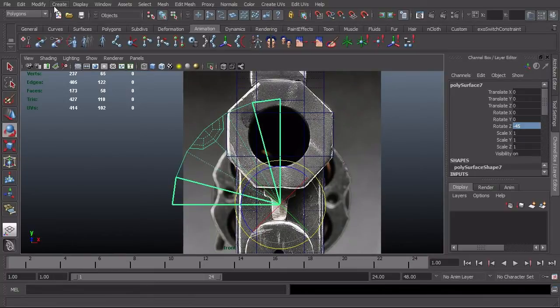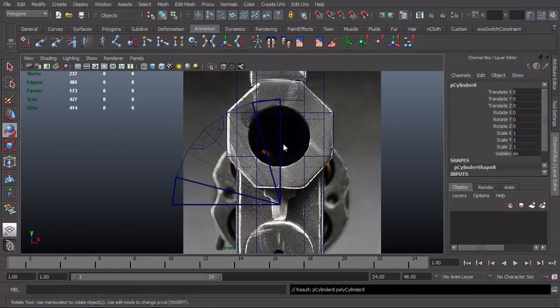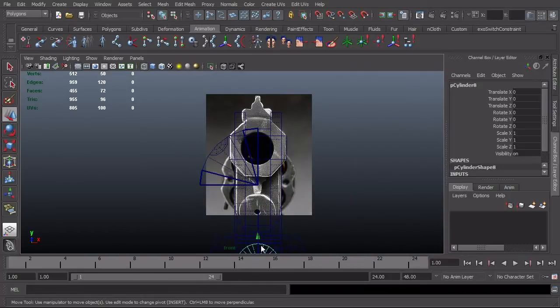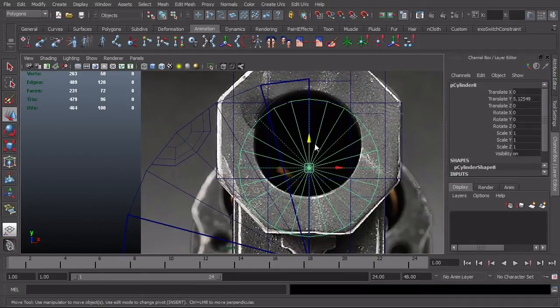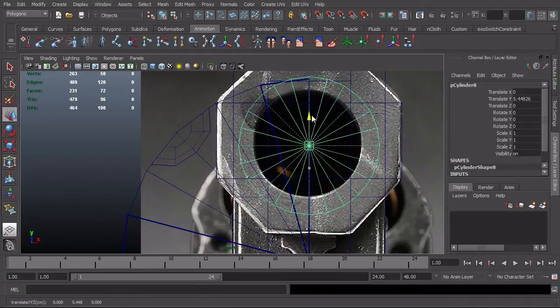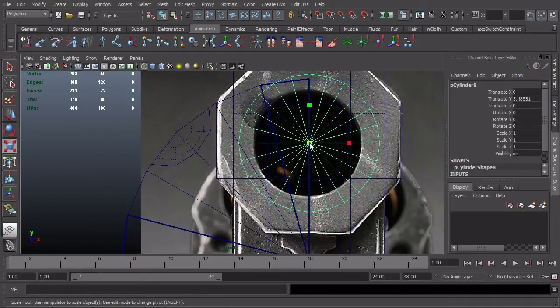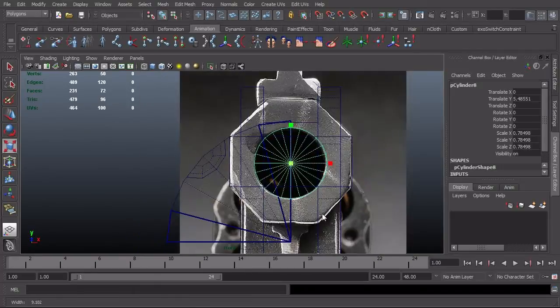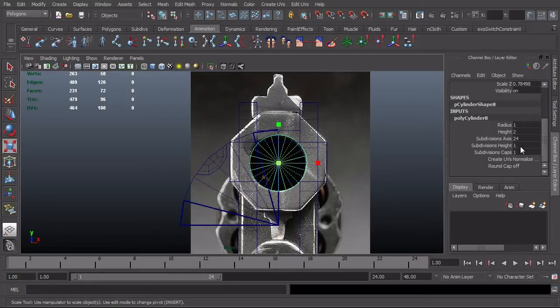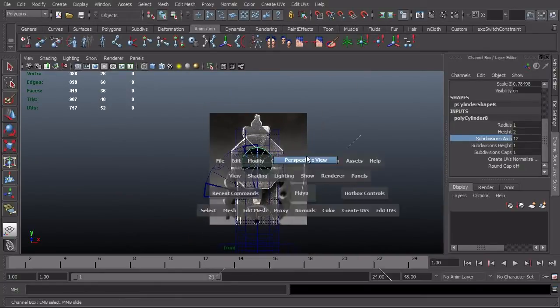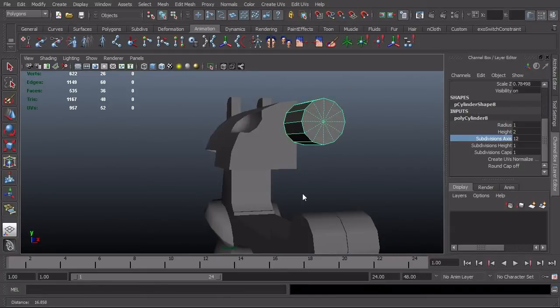So go ahead and add a cylinder for that there. This should be already oriented down Z since that was my last setting. So I'll just be careful not to move this off of X because otherwise it won't mirror properly. So I'll just scale this down and match the height, and if it's off a little bit left to right, that's okay. Which it is, but it's not a big deal. So that's the right size. Now I just need to set the right resolution. So again, you want to be aware of your relative resolution. That actually might look fine at 12. Let me just pull out here to take a look.